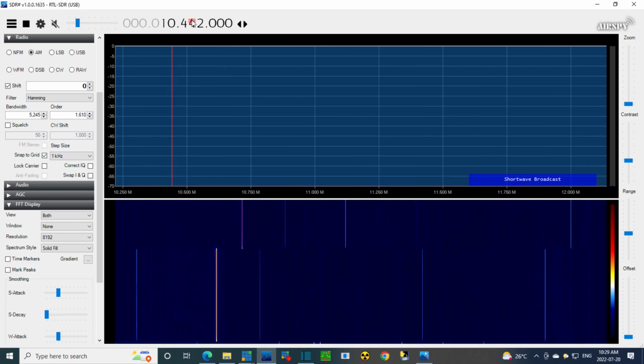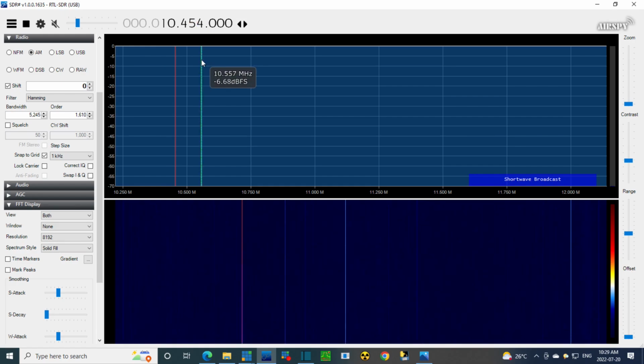So we will work our way up there to 10,455. We'll put the red line where it should be. We should be finding a local oscillator where the red line is. It should be a nice yellow. There's a red thing over here. Okay, so I'm going to tune the radio slightly and we'll see if anything moves. Sure enough, there's the local oscillator. So again, alignment is out.